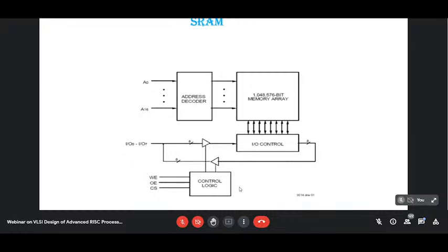So you select a particular row and read the data or write the data onto the particular row by this logic. So this is simple, this is the memory design. Once you do this entire design, then write a Verilog or VHDL code. You can jolly well test it. In fact, using Xilinx software, write the Verilog code and test it and simulate it. That is quite possible. Just at home, you can design and test it.